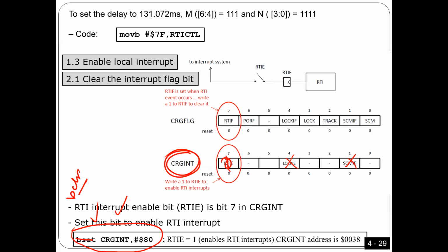Okay, so what does it mean to disable RTI? I'm going to tell you. Look here, guys. RTI is going to do flashing, right? Because every 1 second you are going to flip the LED. So if you disable RTI, it means I'm not going to execute the subroutine, even if you trigger the interrupt. That means there is no flashing. Very simple. So you suspend, pause, or stop the task, whatever the task is. You got what I'm saying?